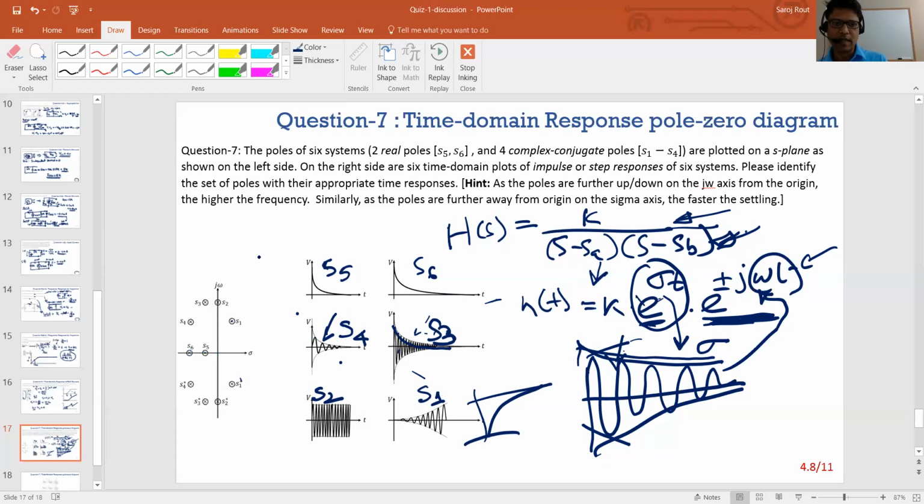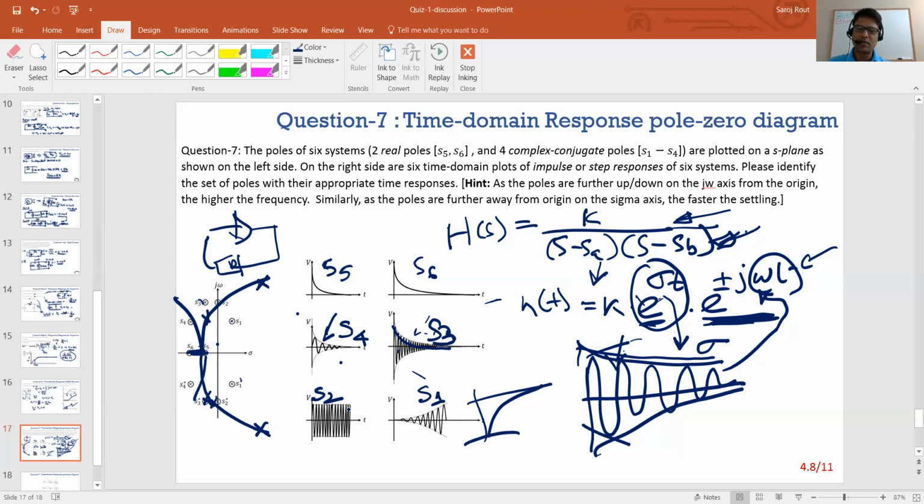And if you've probably done feedback systems, where you have a system of poles and you put a beta feedback, you will do the root locus. You'll take these two real poles and split them, and if your system becomes unstable, they'll split way far down here. If they're here, you'll get ringing. If they go in the other direction, it's so damped and so on. So it's good to have a pictorial view of your pole location, because when you're designing feedback systems, you'll always be trying to find out what your dominant pole is, and if it is complex conjugate, where the location is. So it's a good tool to have.